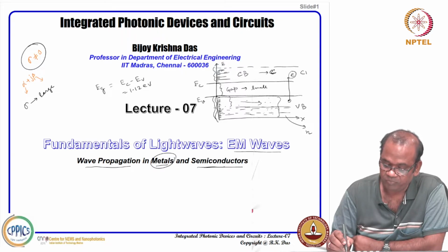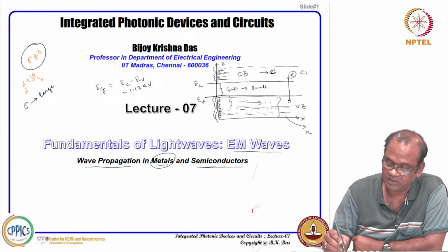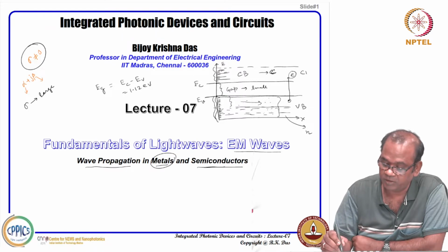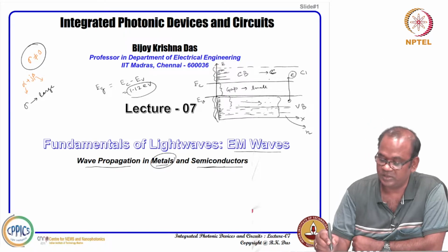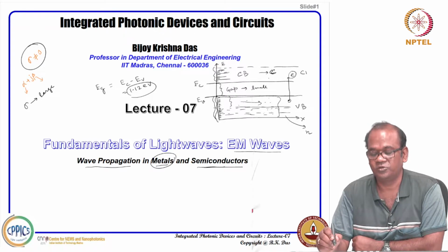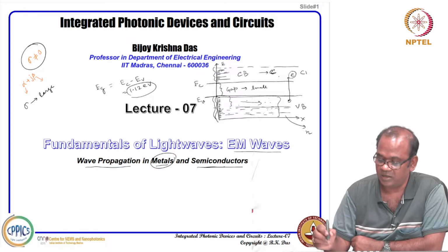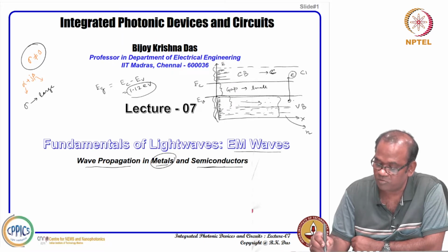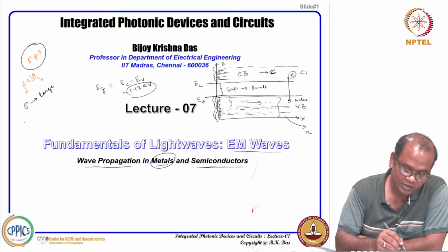So, it will be silicon up to here. You can see some kind of band that is called the valence band, and then there is a gap of 1.12 electron volt, then you can have a conduction band. So, some electrons can easily overcome this 1.12 electron volt at room temperature, and they can occupy the conduction band. So, that is why some carriers will be there in the conduction band, and some so-called holes will be in the valence band. So, in that case both electrons and holes can contribute.